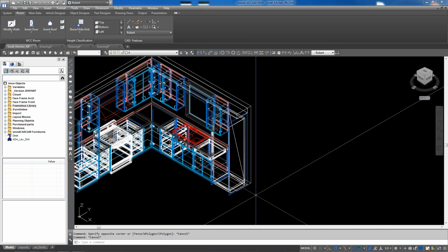I wonder if we could add those blocks to our main library, so in the future we just have them and don't have to pick them up again from a website. Yes, you can, and in fact, you can even add a generic refrigerator, generic stove, generic microwave, and it can be parametric to a space. They're pretty easy to add. So you've got the block of this refrigerator. Just go ahead and open up that drawing block.